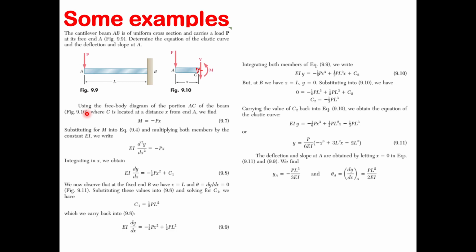But in a regular analysis, you have to take the derivative of y with respect to x and then find the location of that maximum deflection, plug that back in the main equation, and then find the relationship between the load and E and I and the length and all of those things, essentially.